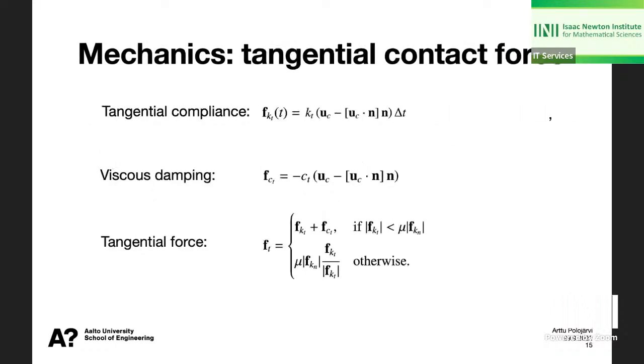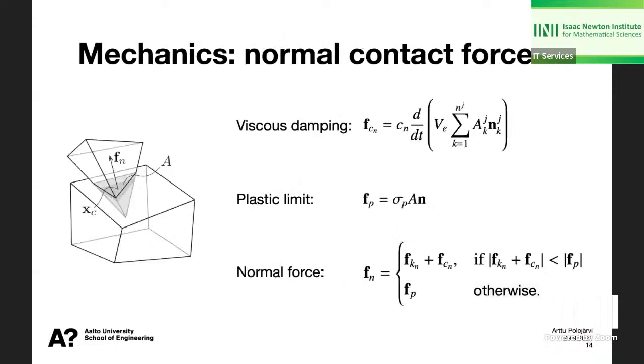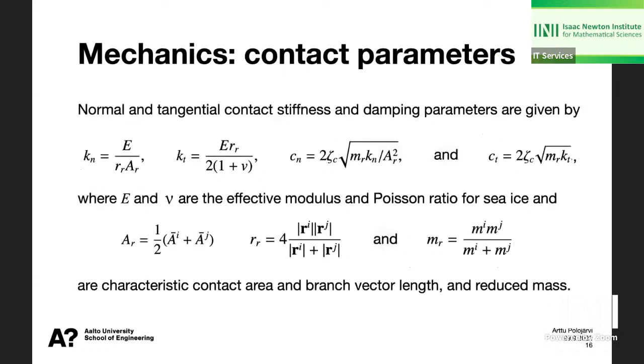What you see in all of these equations are these contact stiffnesses, KTC and KT, and damping parameters. It's often discussed how to define those. Well, I found a way to at least say that in some simple cases I can pretty accurately define them based on the actual material properties of ice, or material properties that I could measure. It's obvious that they are estimates in many cases, but for certain cases, things work quite nicely when you define them like this.